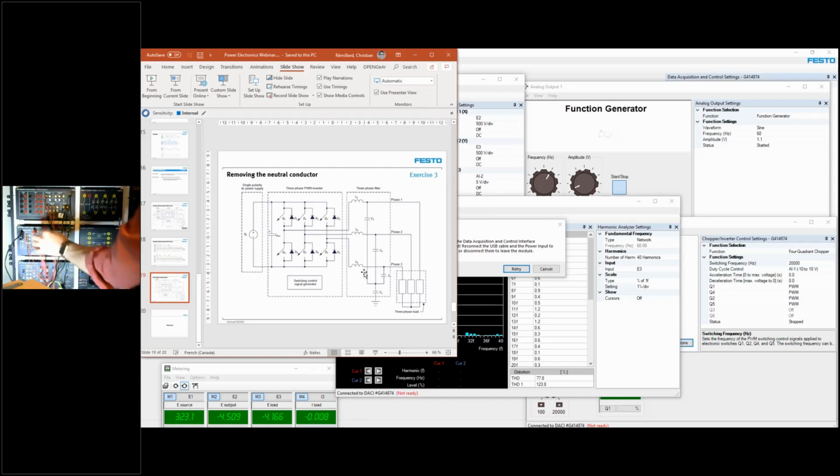So here is still my DC input to my bridge, output of phase 1. I will go to ammeter 1 here, and from ammeter 1, I'm going to the first phase of my induction motor. The other two phases, I will not be measuring their current. I will go directly from the output of the inverter to the corresponding phase.